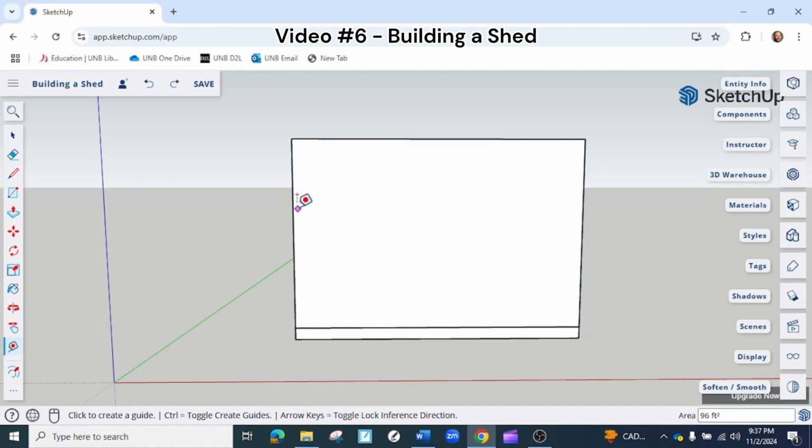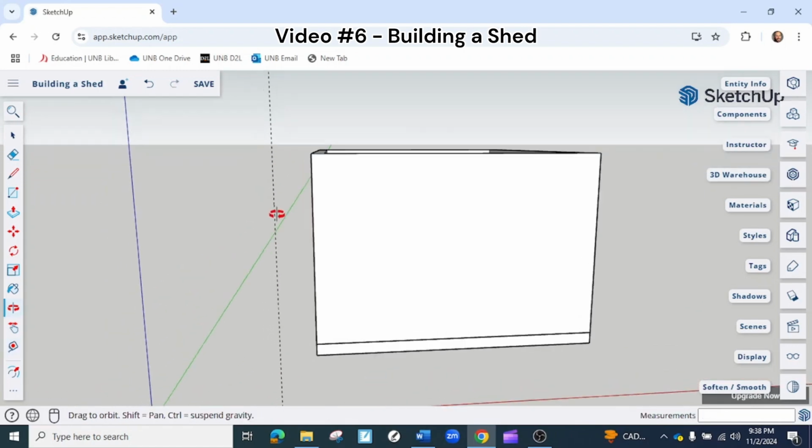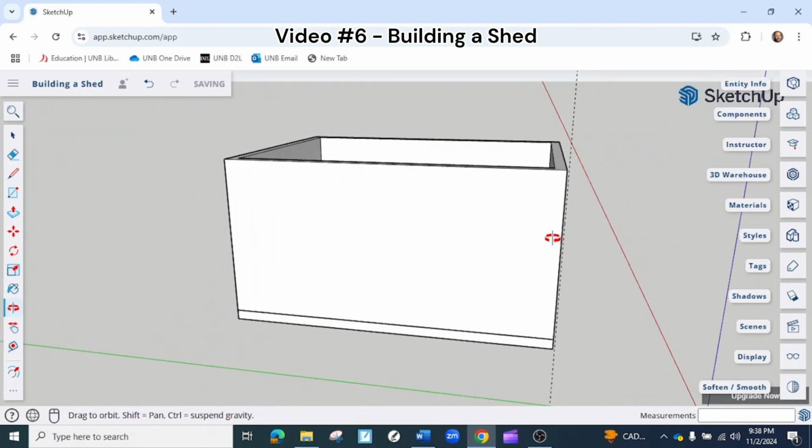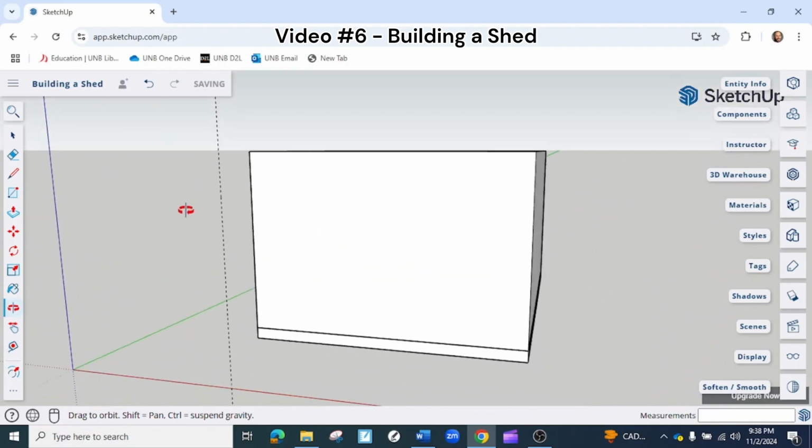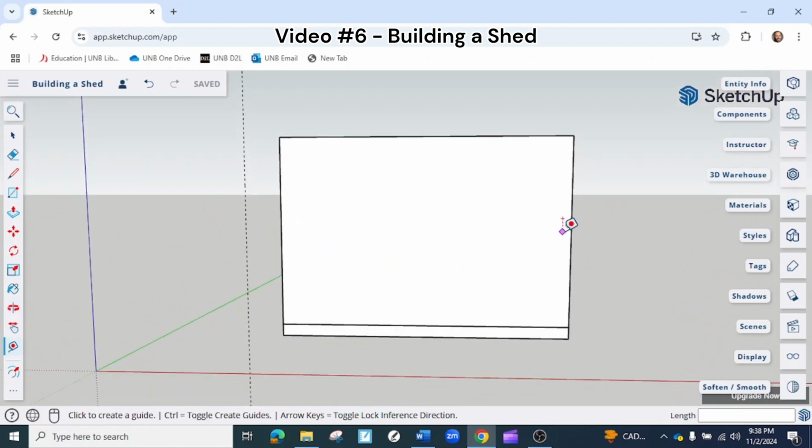We're going to start here on this edge, and we are going to say, I want my roof to come out 18 inches. So click with your T tape measure, click here, release, drag it out, it's in edit mode, and type in 18 quotation marks down in the bottom right corner, which is of course going to pull that out 18 inches. So that guideline is now 18 inches out from the side of the wall. Let's do the same thing on this side. So start over here, drag it out, type in your 18 and enter.